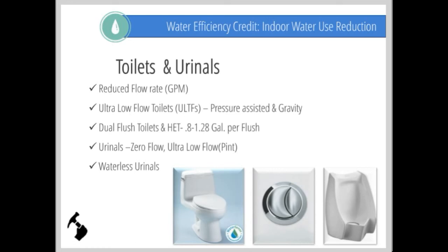Though some low-flow toilets give problems, today's low-flow toilets are much more effective and efficient, and their parts are more durable and replaceable. There are also ultra-low-flow toilets, or ULFTs. Ultra-low-flow toilets usually use one of two methods to clear waste: gravity or pressure-assisted. Though pressure-assisted toilets are efficient, they do make a bit of noise compared to traditional gravity ones.